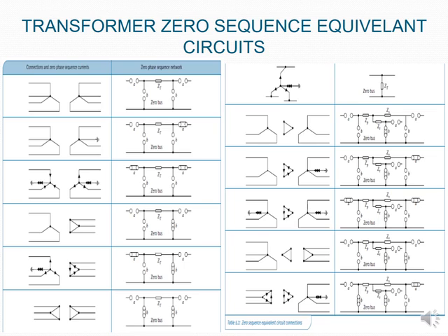Then if you have one where one has just got the neutral and the second one has got your neutral connected to your earth point, then you see the difference from the above one is that where there is that earth point neutral connection, you've got an impedance that you can connect into that part. So that circuit becomes closed and no longer an open circuit.